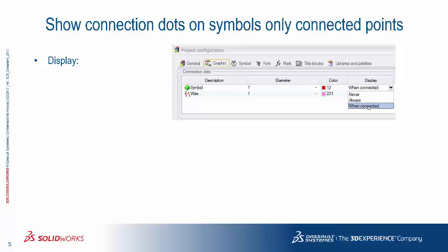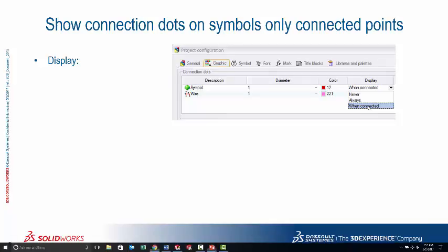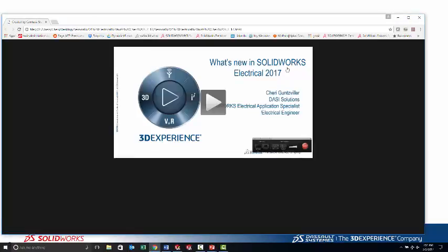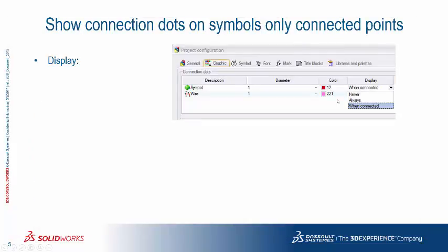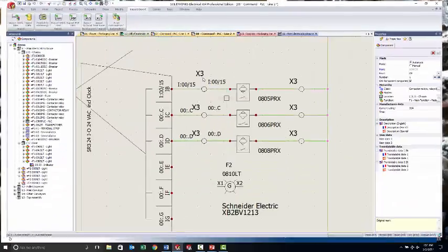Now, if you think about CAD, you didn't have to use snap and you didn't have to use grid, so your lines were not necessarily always at that point where you were straight. I've got people that do that on a regular basis, and then they wonder why the wires didn't cut, because their symbol was slightly off compared to their wire. Now, there's two things that they did here, which is really kind of cool.